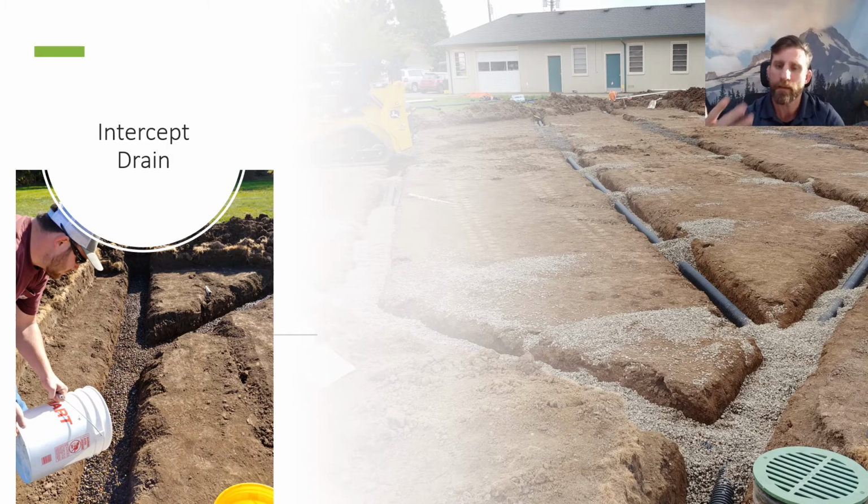All right, here we see another example of an intercept drain tile system. So this is a project out at Lewis Brown Farm where we were renovating one of our research turfgrass areas. So here you have the native soil, and then you've got a series of lateral drains and then a main drain here where water can move through this part rapidly, and we're putting gravel over top of the drain lines there. So you've got the drain lines filled with gravel over top of the drain tile.